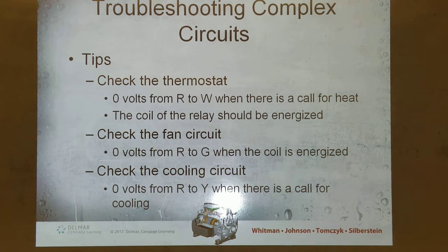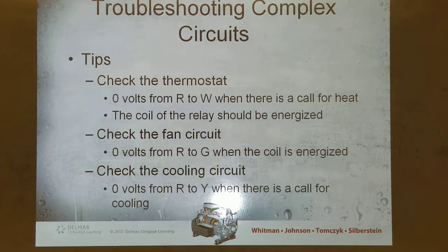Remember from last week that the thermostat is what? A switch. A bunch of different switches, right? Okay, so it's gonna pass power. So how do we know when it's open or closed? How do we know when stuff's on or off? By checking across the terminals. It's gonna tell us whether the switch is open.